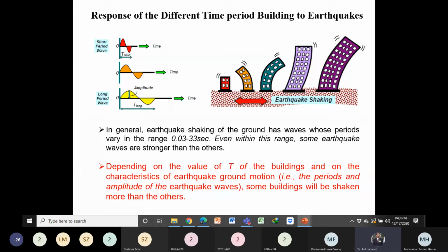You can use the mechanical means. You can use the shear wall. You can provide the bracing, and you can use the dampers. You can use the mechanical means to improve its performance. But then you can tell the client that this option will be costly.